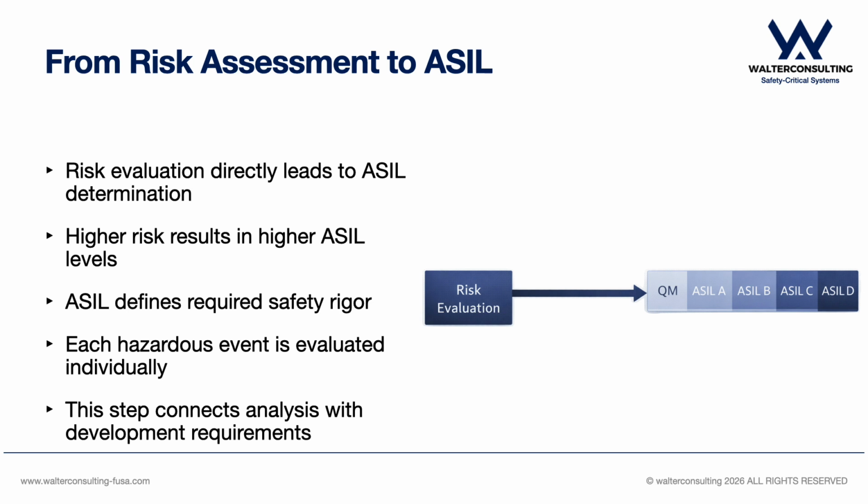But here is an important detail. This evaluation is not done for the entire system. It is done for each individual hazardous event. So every hazardous event gets its own ASIL classification. And this is what connects HARA with the rest of the development process.